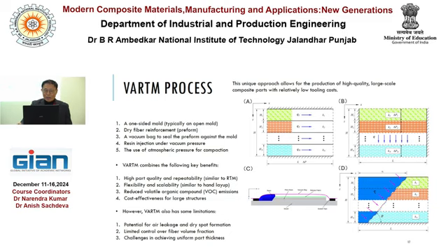And VARTM combines the following key benefits. High part quality and repeatability, similar to RTM, and flexibility and scalability, similar to hand layup, and reduced volatile organic compound emission, and cost effectiveness for large structures. So large structures are emphasized for this process.